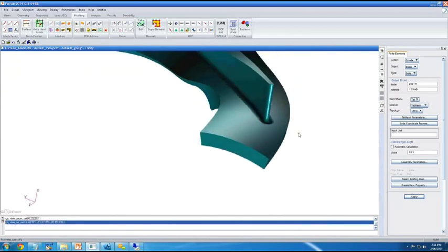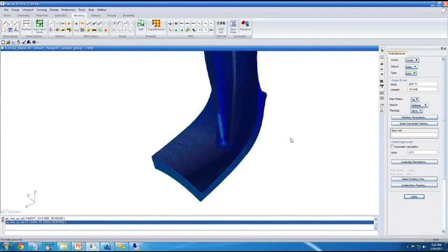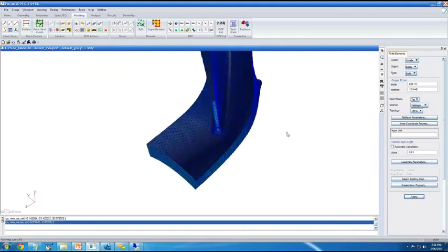So the route that I showed, where we manually made the changes to the solid geometry and exported both the BDF as well as the edited Parasolid, is a good process to follow if you wanted to use the association of any of these faces to apply loads.